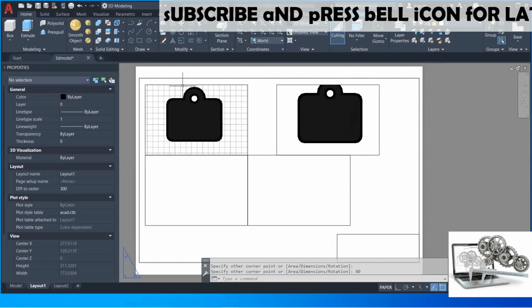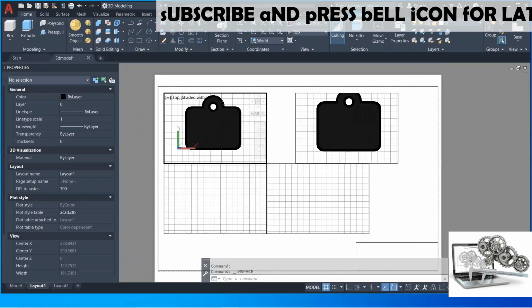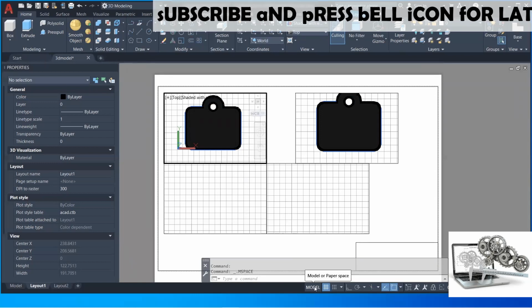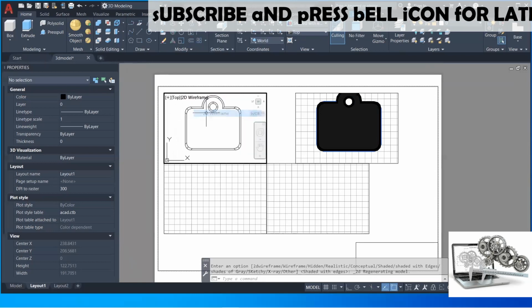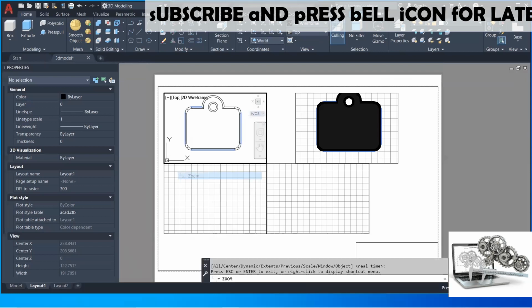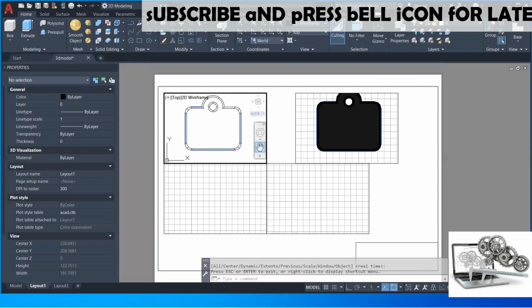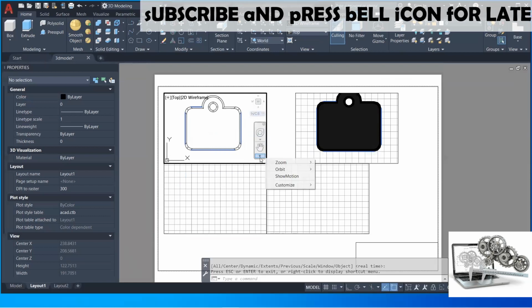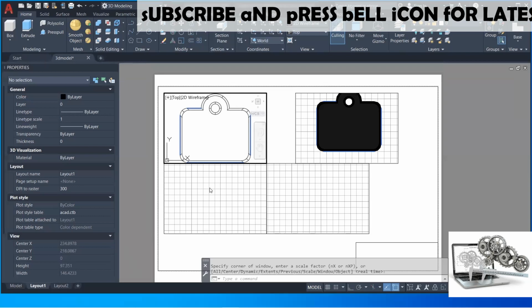Now we have to set all these viewports according to our requirement. So first we are going to change the appearance and the scale factor. Just double click inside the viewport and turn the grids off. After that, change the shading style to 2D wireframe. Zoom it to the extents. The same thing you have to repeat for all the viewports which you have created.